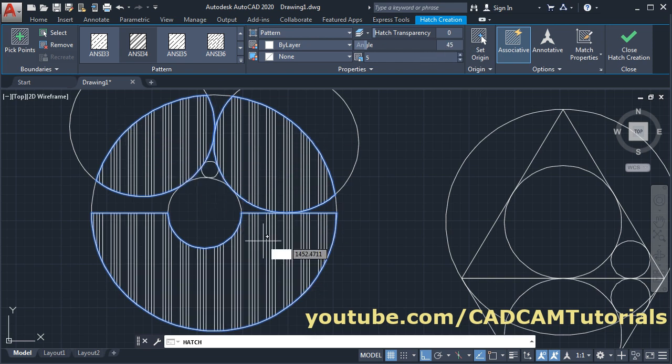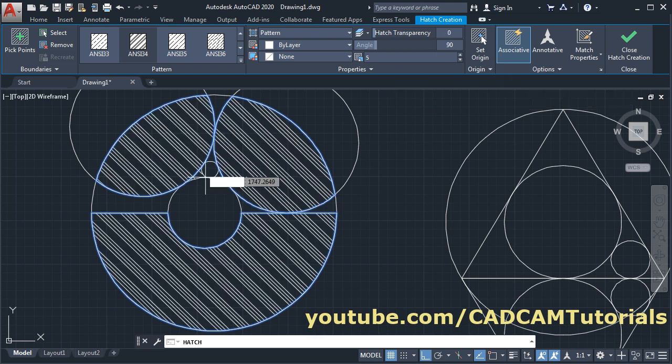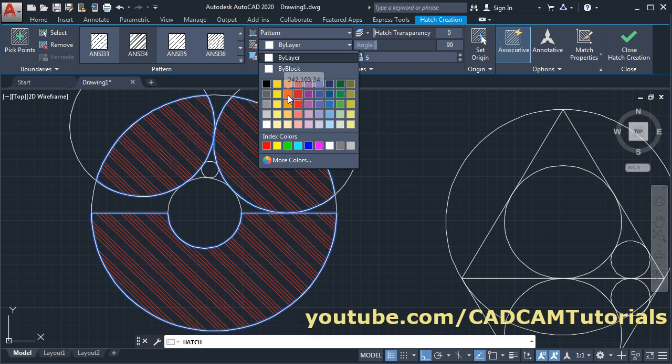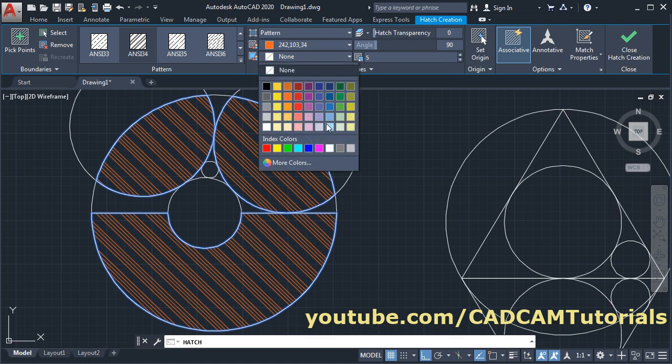And if you want to make it opposite, then here you will have to give an angle of 90, enter. Then it will create the opposite hatch. Then if you want to change the color, click here, and from here you can choose your desired color. And if you apply some background color, then from here you can choose the background color.